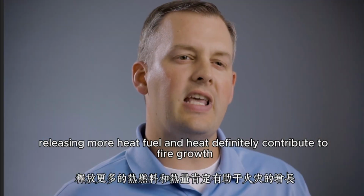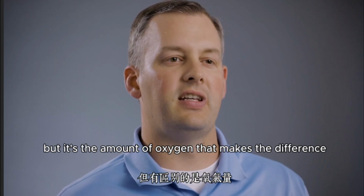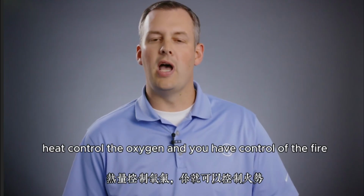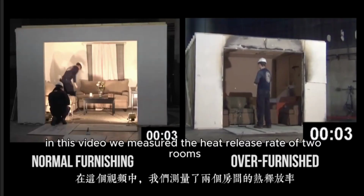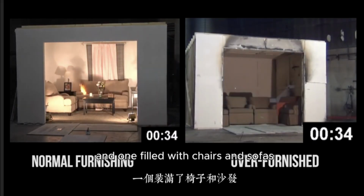Fuel and heat definitely contribute to fire growth, but it's the amount of oxygen that makes the difference in how fast fire is allowed to release heat. Control the oxygen, and you have control of the fire. In this video, we measured the heat release rate of two rooms. One furnished like a typical living room, and one filled with chairs and sofas.